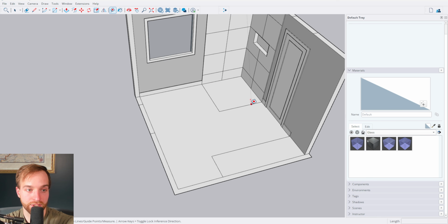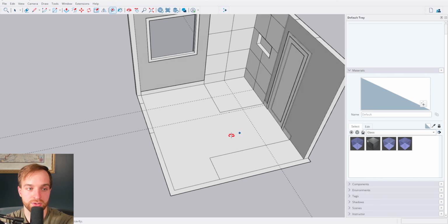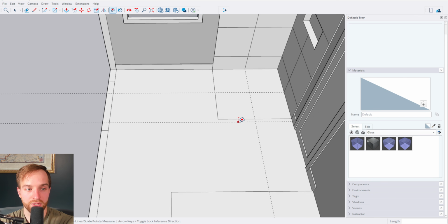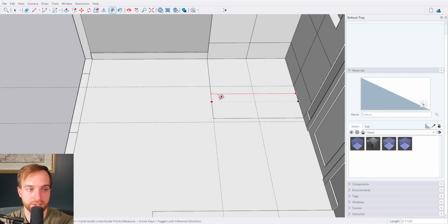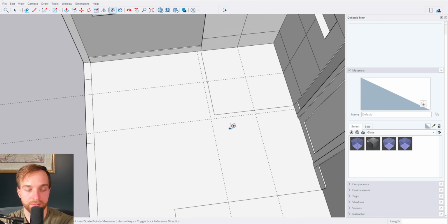So let's say the floor tiles are going to be the same as these wall tiles. A really sharp look would be to see if we could just keep this all consistent. So the only problem we're going to have here with this specific design is that if I wanted to have this be a full tile, well, it's not because our shower isn't 48, right? So if I actually went to 2 feet, we would have a little sliver piece here, a sliver piece here.